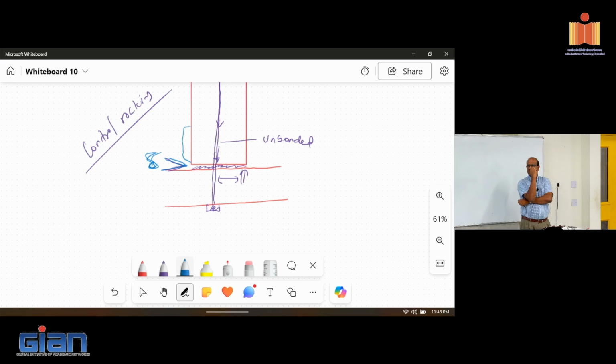Now, I have a question regarding practical implementability. Will this type of scheme be used for one specific wall in a building as a master wall, or will it be used in all the walls? Typically, what the precasters have done in the US is identify the walls responsible for resisting the seismic load. Depending on the load, they may pick, in one direction, four walls that have to do this. Then they will design them to be like this.